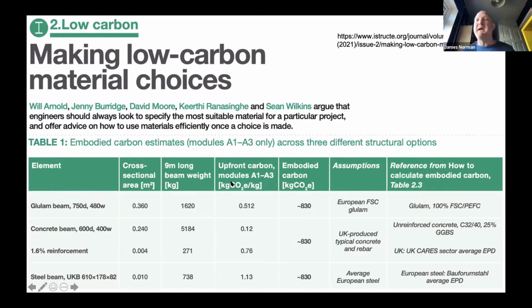Now, a beam that's 9 meters long, I can tell you straight away that timber is not going to be the right material for that design problem. It's going to have all sorts of things that you would want to consider. And this is where, if you start with the wrong question, if you start with the wrong assumptions, you're not going to end up in the right place.